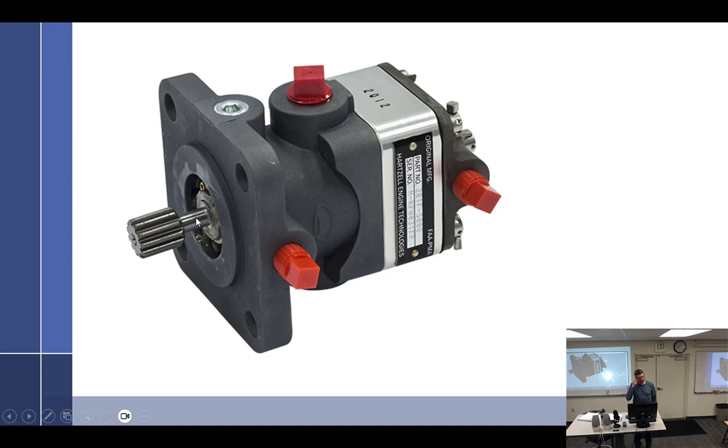I was working on a Skymaster once upon a time. And the guy complained that his vacuum pump wasn't working. So I pulled the vacuum pump off, grabbed the new one out of the box, because I was told to, and put it on, but the splines didn't line up. So I was moving the engine propeller, trying to get the splines to move so I could put it in there, but the splines on the engine never moved. So guess what happened? It sheared on the inside. I made a lot of metal inside.